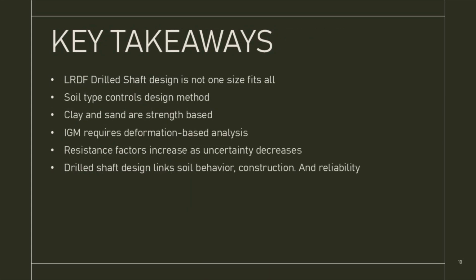To summarize, LRFD drilled shaft design is not just an exercise in plugging numbers into equations. The soil type fundamentally controls the design method, how resistance is mobilized, and which assumptions are appropriate. In clay and sand, design is largely strength-based and relies on empirical correlations such as alpha factors, beta factors, and SPT values.